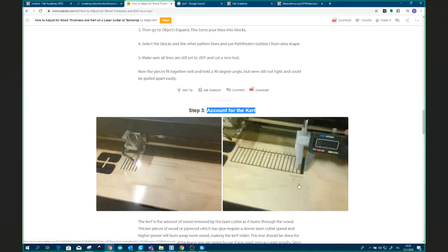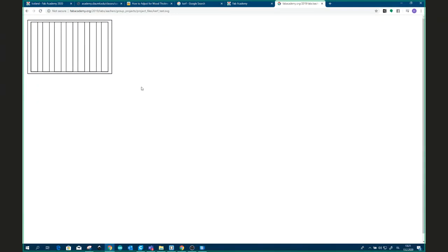So what you can do is you take a design file, you laser cut rectangles up to maybe say 14 pieces. Then you measure the change in difference and divide that by the number of shapes you've made. Here is a simple example. For example, you need to cut this out and then put this all together and measure the difference of the laser beam. And we should do that all together in our individual labs and document that process as well.